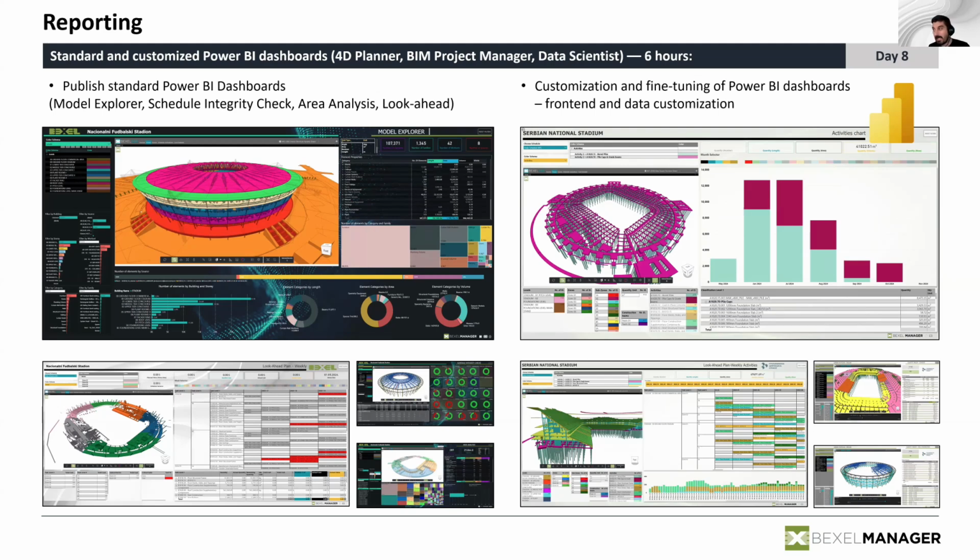So they could see not only the numbers of executed works or how the schedule stacks against the DCMA analysis, but also the projection of that data on the model. If we say these are the quantities of concrete to be executed in the next 3 months, they see exactly to which elements these cubic meters of concrete will be mapped.